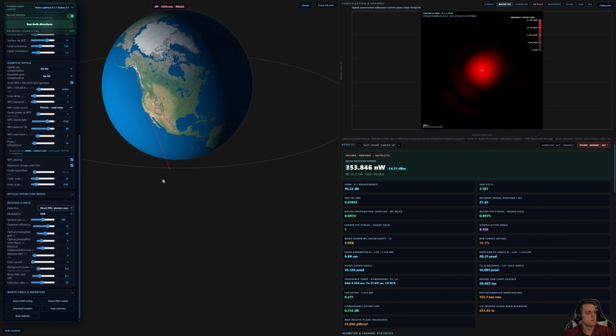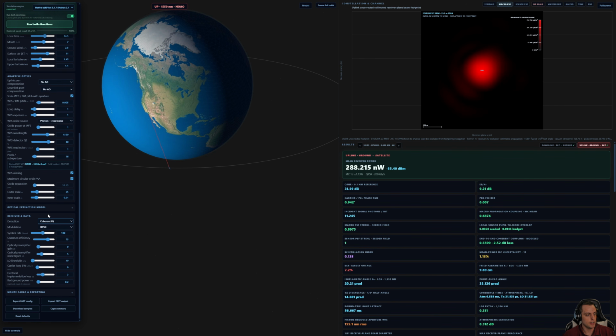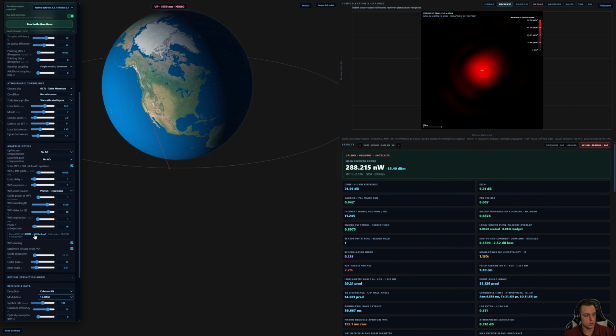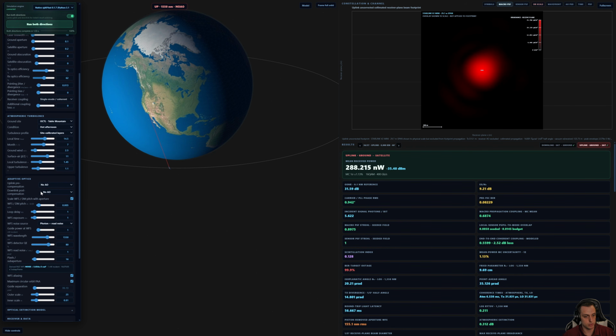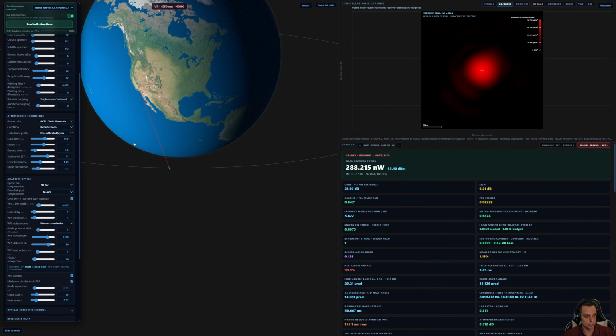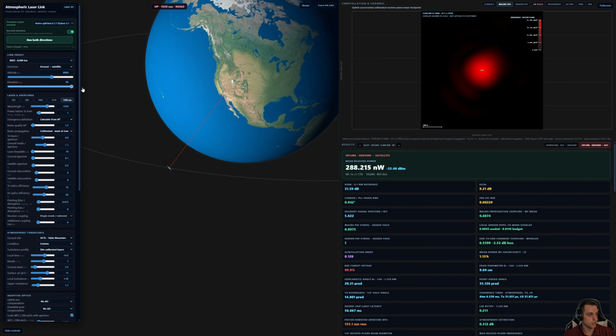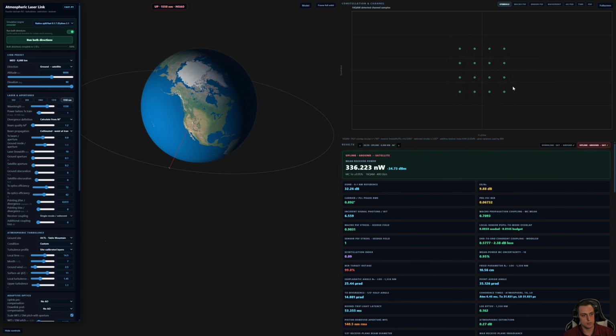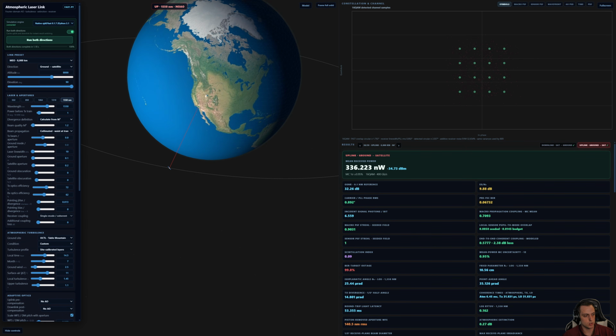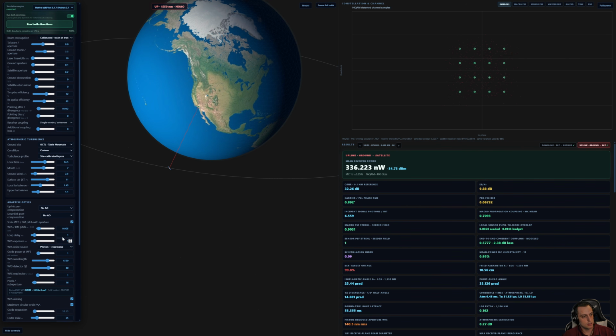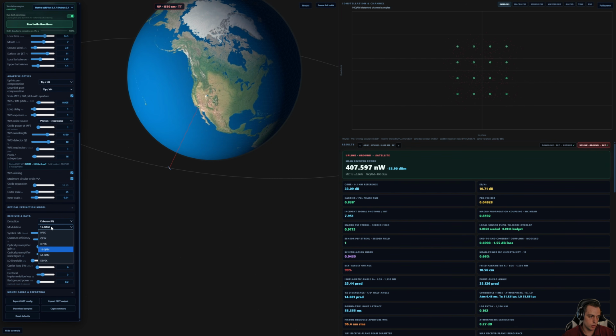And potentially you would want to go back to coherent, and try higher order so that you could have more bandwidth efficiency, more spectral efficiency. Although this will give you sort of questionable conditions. Let's try with better elevation. Yeah, even with good elevation, this would be questionable without adaptive optics. And even with tip tilt, this would be pushing it. So unlike in undersea cables, you probably wouldn't want to go higher order QAM. You'd probably want to stick with QPSK.